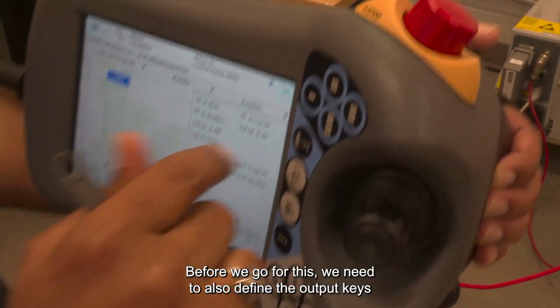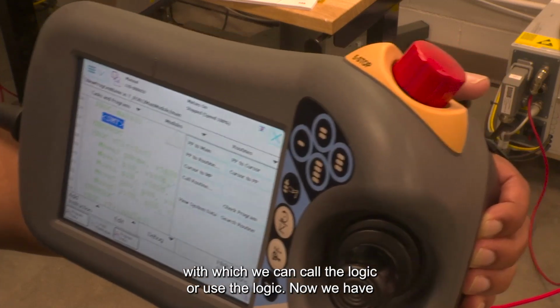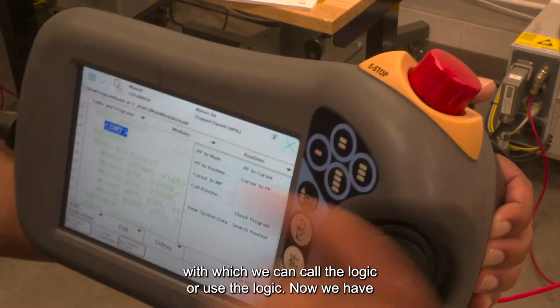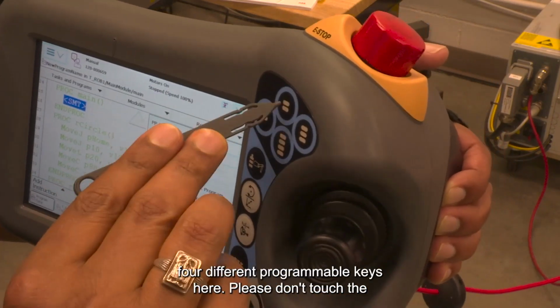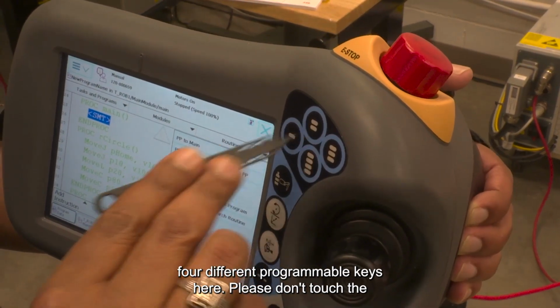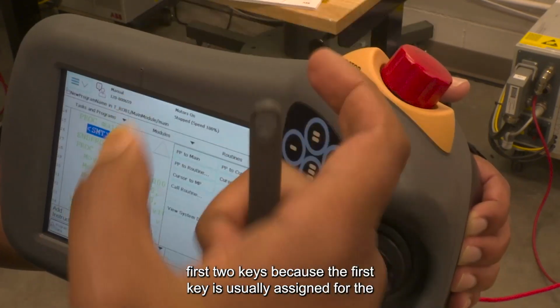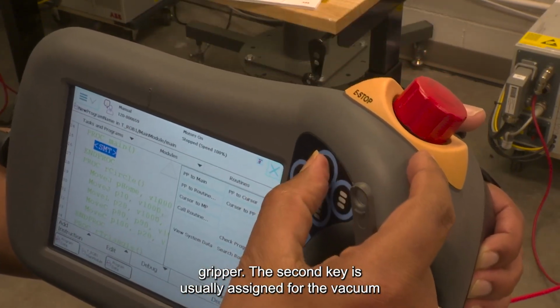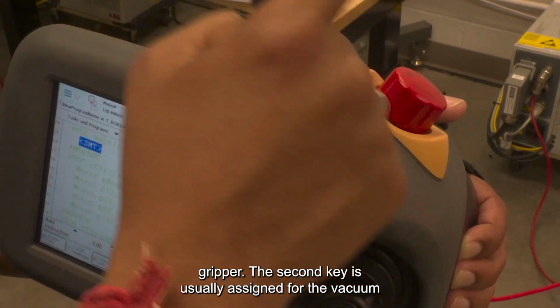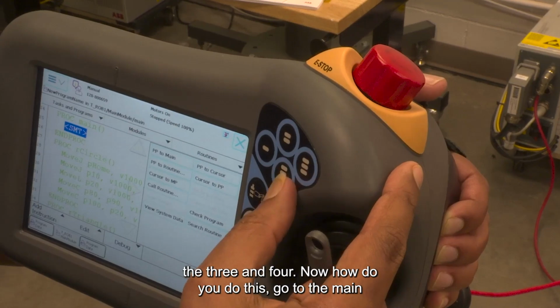Before we go for this, we need to also define the output keys with which we can call the logic or use the logic. Now, we have 4 different programmable keys here. Please do not touch the first 2 keys, because the first key is usually assigned for the gripper. The second key is usually assigned for the vacuum of the gripper. Do not touch these 2 things. We will only see the 3 and 4.